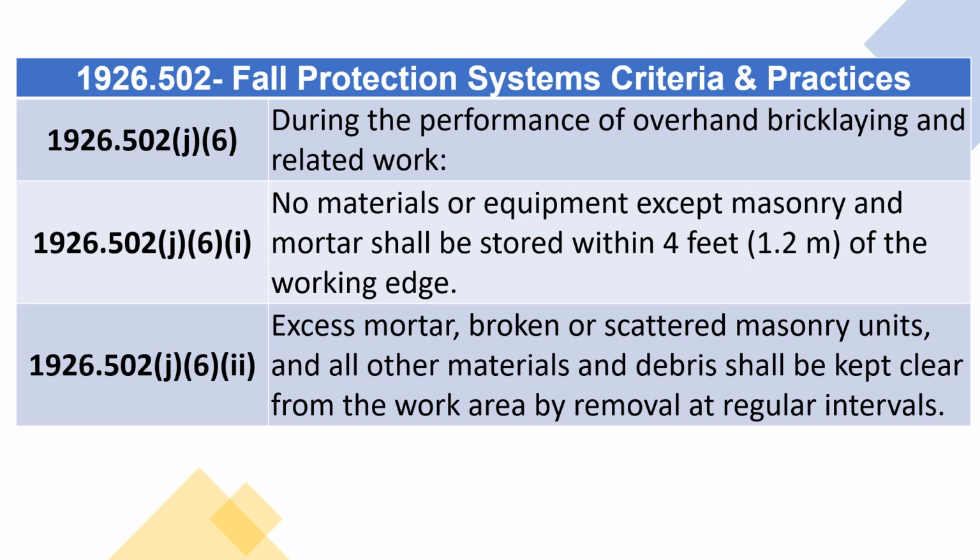1926.502 J6. During the performance of overhand bricklaying and related work: J6 (i). No materials or equipment except masonry and mortar shall be stored within 4 feet (1.2 meters) of the working edge. J6 (ii). Excess mortar, broken or scattered masonry units, and all other materials and debris shall be kept clear from the work area by removal at regular intervals.